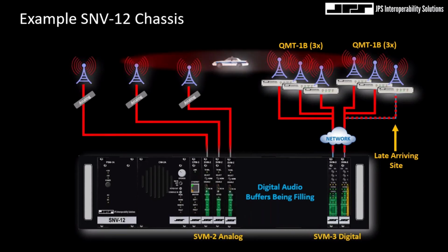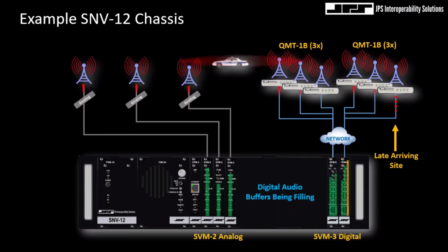timestamped, and the CPM3 control processor module will monitor each of the unsquelched receive audio streams and will force all site voter module interfaces to begin buffering or storing receive audio. When the last receiver site delivers its audio with the timestamp, the captured spectral noise for all eligible site voter modules will also be compared.